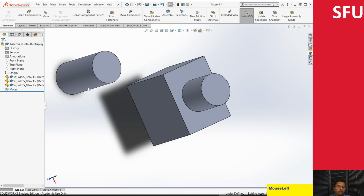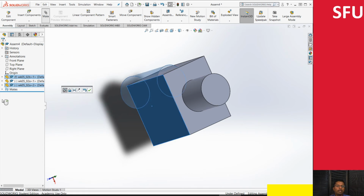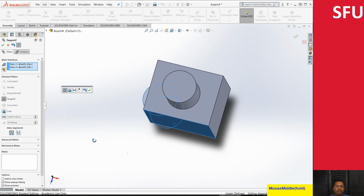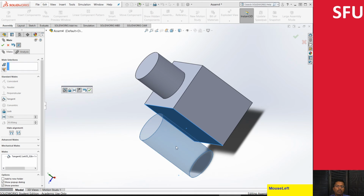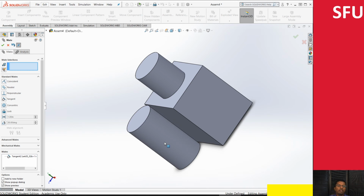And so what I can do is take this surface and this surface and wait for the mate. If it didn't show up, we can do this. So now it's going to assume that it's a concentric constraint. So now the cylinder has gone inside, right? Face I selected. So I can flip direction, which will bring my cylinder on the outside. And then I say, okay. So now the cylinder can move on the surface of the object. So this is not very useful for this very simple example, but you can use it for more complicated constraints.